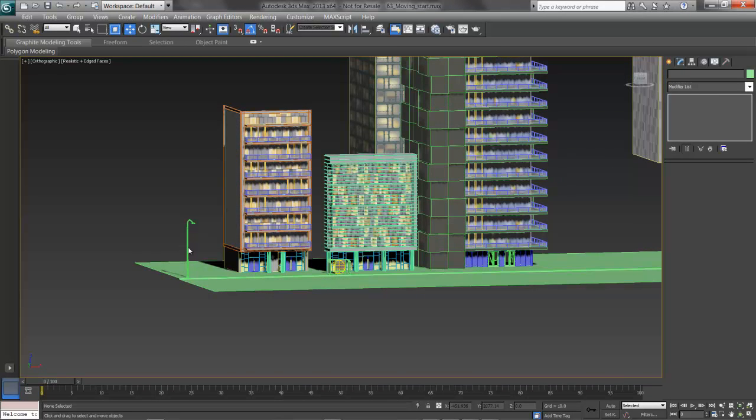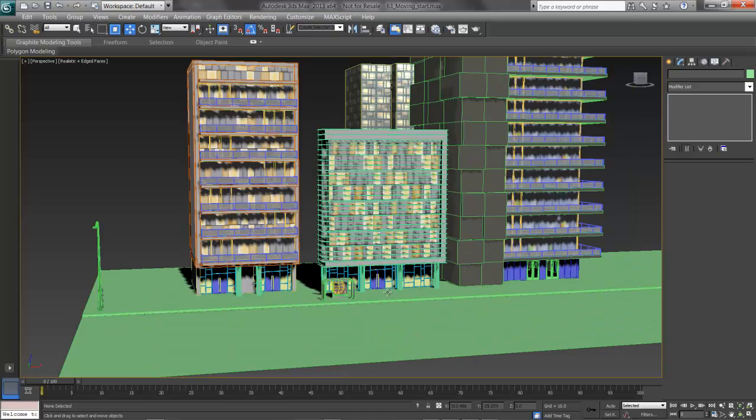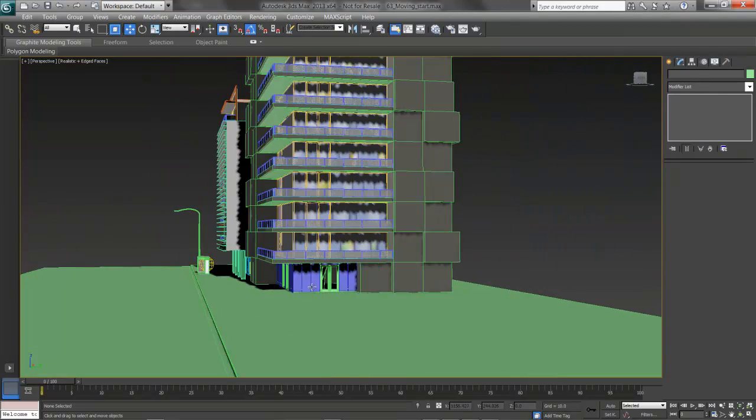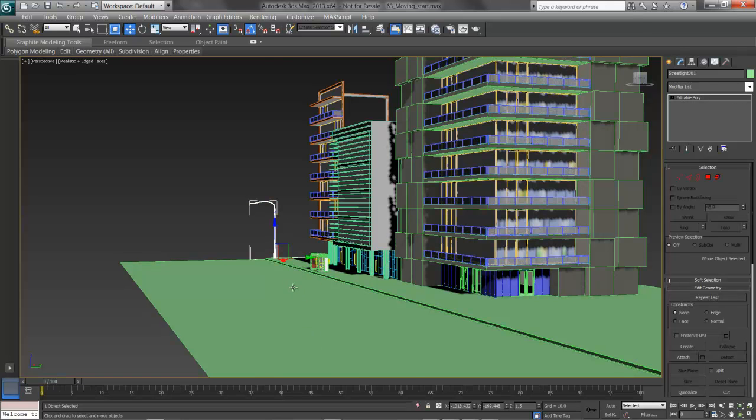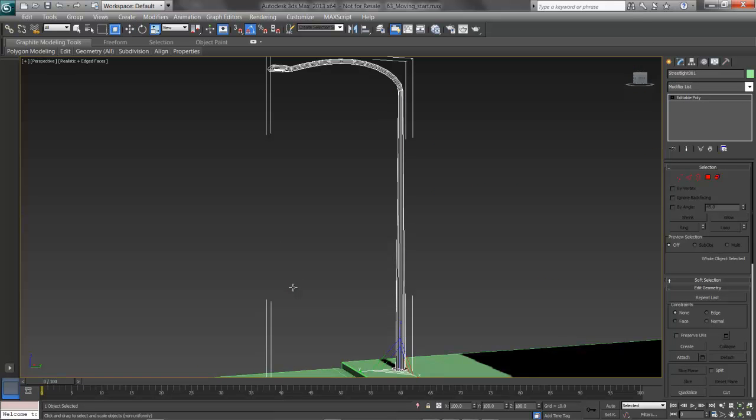If the streetlight feels too tall, you can scale it just a little bit. Right now, for example, if I look in a perspective view by pressing P for perspective and spin around onto the street, it feels like maybe this streetlight could shrink just a touch, so it's a little more intimate here, as it's very tall next to the bus stop. I'll select it, press Z to zoom extents, and press R for scale.